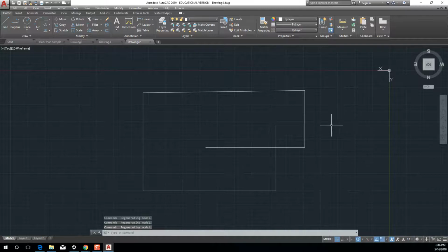Now the problem with what I just did is I did end up back in a top view, but do you notice that top is upside down, right? So I didn't reorient my drawing the right direction. It's kind of upside down right now. And also what this view cube does is it creates a top view, but it's a top perspective view of this drawing, which is really a confusing idea.